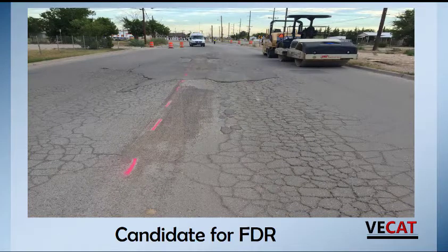So here is an example of an FDR project or a future possible FDR project. Notice there's a lot of different asphalt problems going on here. We've got some patches, we've got some rutting, and we've also got some alligatoring and cracking. The mix design needs to include all of these problems. We need to have samples of the new asphalt from the patches. We need to have samples from the rutted spots and the alligatored spots to know what's underneath of them. That way, if we've got a base failure, we can correct it when we go through and do this and not pretend it didn't happen.